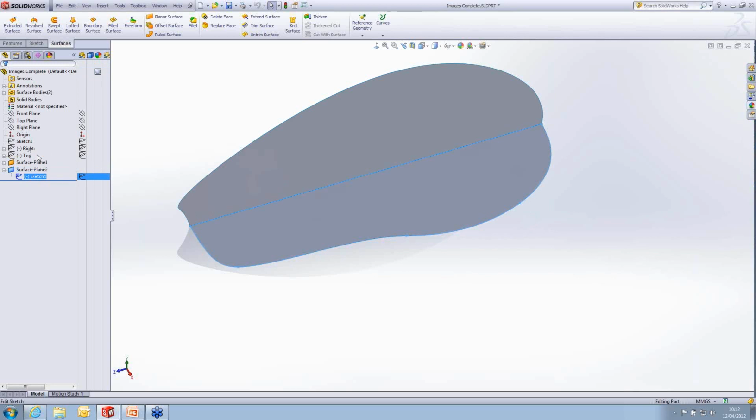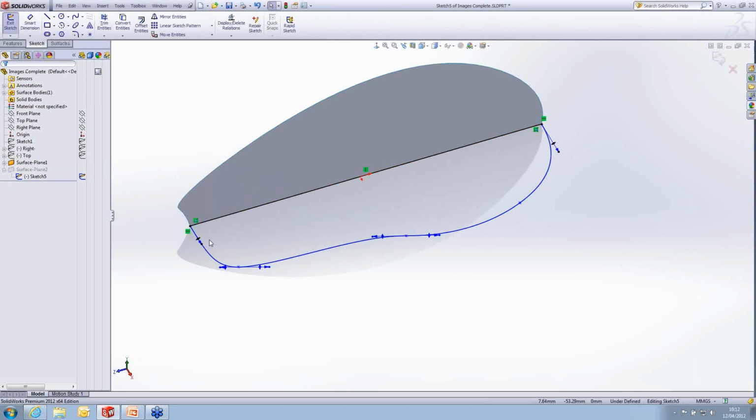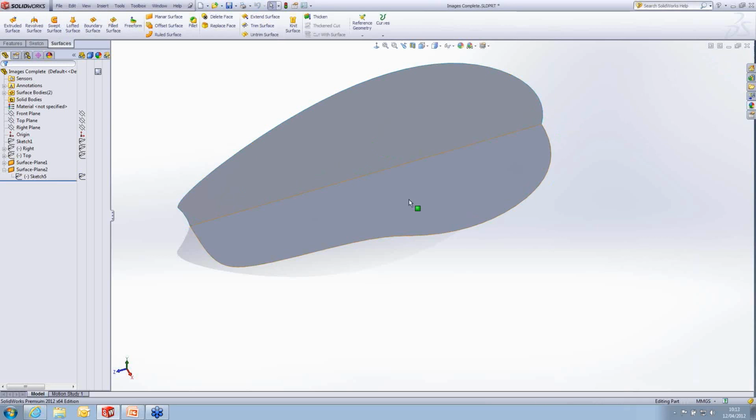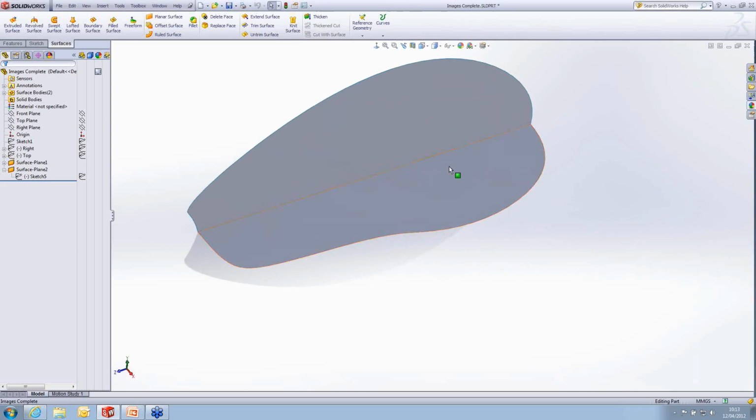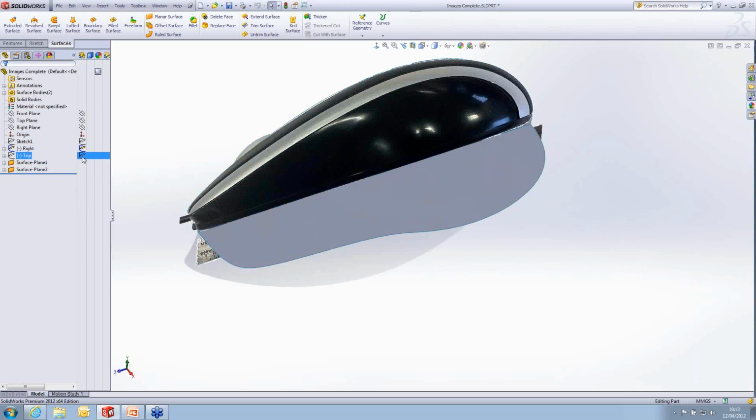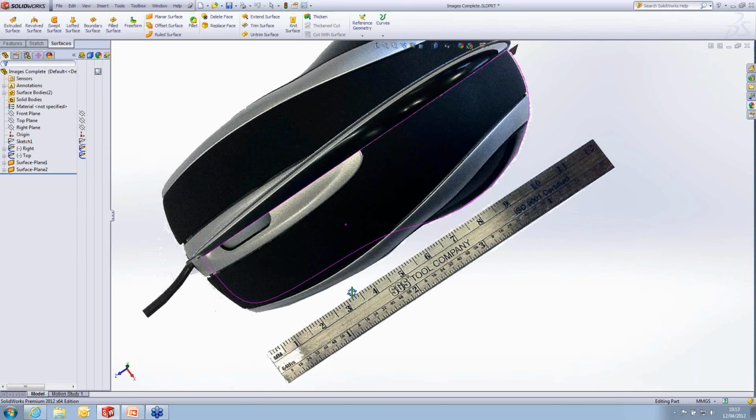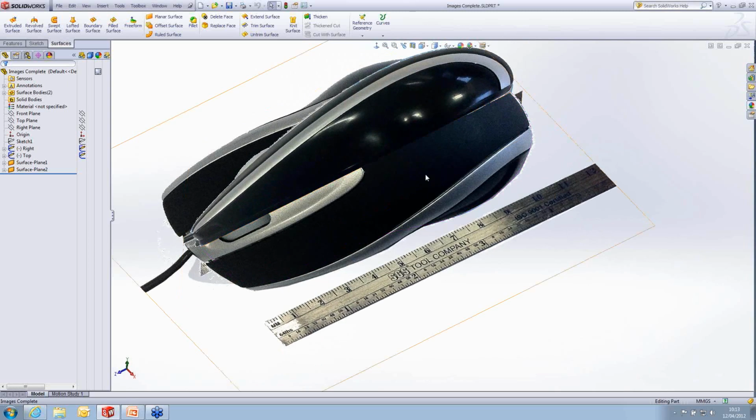We have a look at that sketch just to see how that was created. Again, that was using splines, but the only thing I've made differently here is just to make sure that I've got a horizontal relationship where it matches up with that symmetry plane, and that's just making sure that when I actually go and mirror this part when I'm finished, it'll have nice symmetry in the middle area. There's no real point in me modeling the whole design on both sides because it is a symmetrical model, so I might as well just model half of it and then mirror it over.